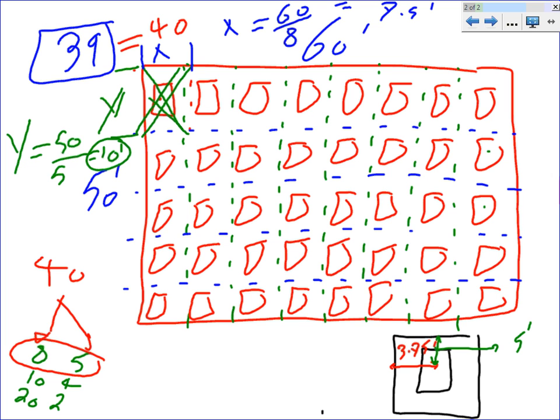Now if it's different, guys, if there's a niche over here that cuts through these 2 lights, I might have to get these 2 lights out of the picture. Just get rid of them. So when you work with light, always work with rectangle and square. Make the room rectangle, even if it's not. Do the calculation based on that. And if there was a niche right here that comes all the way up to here, or cuts through these 3, I might have to get rid of these. Just get rid of them. If the fixture was right through the wall, I just get rid of that fixture.